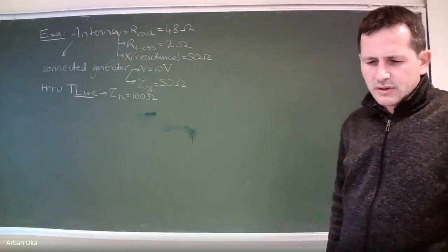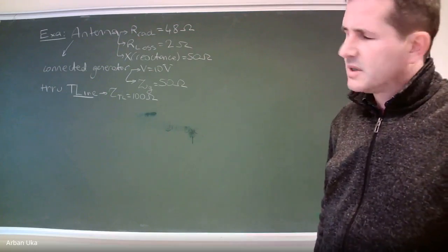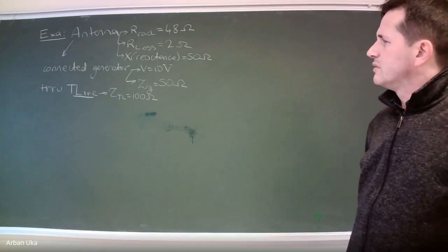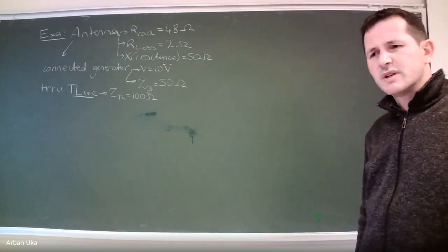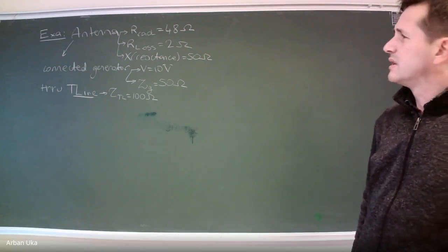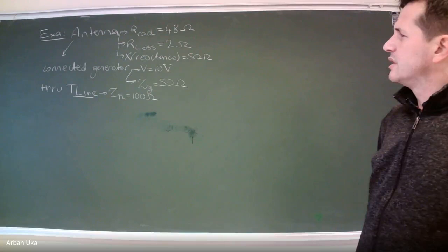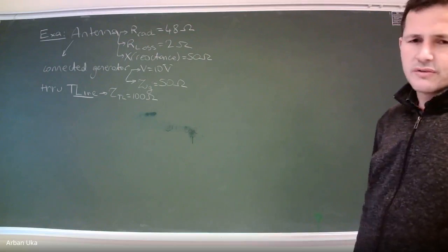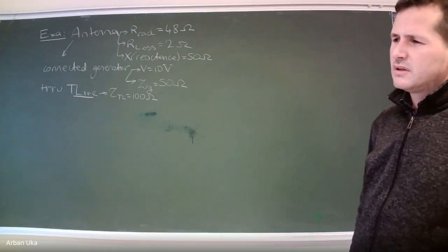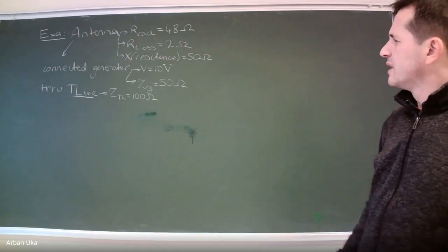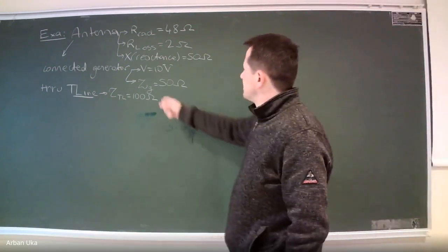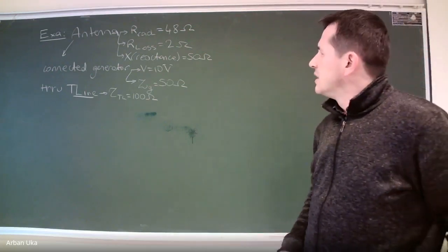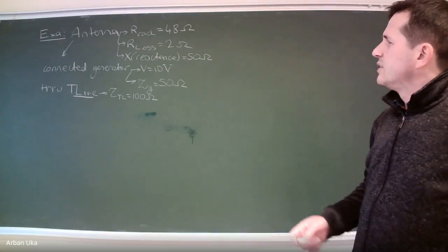often in old antennas, or let's say the simplest possible antennas, the impedance of those is relatively small, which means that there would be a huge mismatch between the old type of antenna and the traditionally used generators that have an impedance of around 50 ohms. Whenever these two are connected, a lot of reflection happens, so there is a very low efficiency, so we lose some information. So you can try to memorize this: something between 50 ohms and 75 ohms would normally be the impedance of a generator.